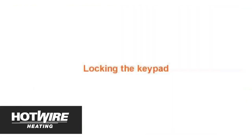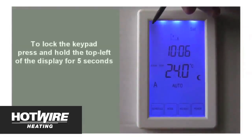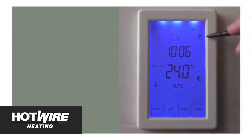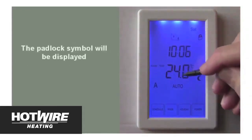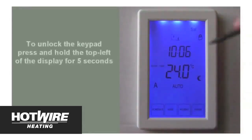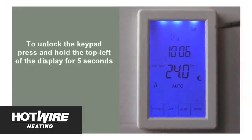Locking the keypad. To lock the keypad, press and hold the top left of the display for 5 seconds. After 5 seconds, you will see the padlock symbol appear, and the unit will become unresponsive. To unlock the keypad, press and hold the top left of the screen again for 5 seconds. The padlock symbol will disappear.